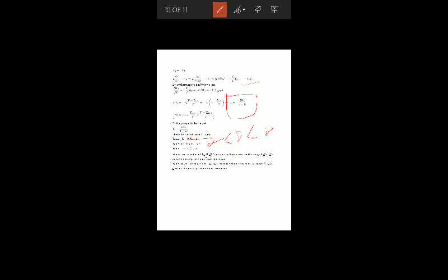So from d equal to 0 to 0.5, the output voltage varies from 0 to Vs. The duty cycle, meaning the on time of the switch, from 0 to 0.5 acts as a step down chopper. When d is 0.5 to 1, the output voltage varies from Vs to less than infinity, V naught greater than Vs, and it acts as a step up chopper, or boost operation. Buck operation means reducing the voltage, boost means increasing the voltage.